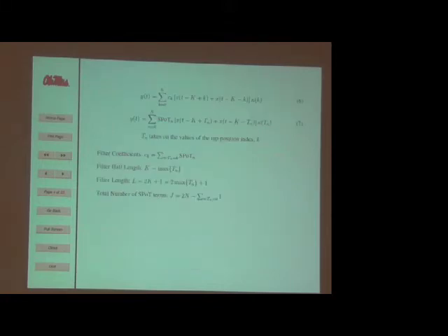So here again is the relationship of those. If I want to know a particular coefficient of my filter, I have to sum over some number of these signed power of 2 terms where this t sub n is equal to k. And of course, if I have a designed filter, I can get back the filter half length by looking over all the p's and k's and finding the one that's got the largest value. And that again sets the total filter length.